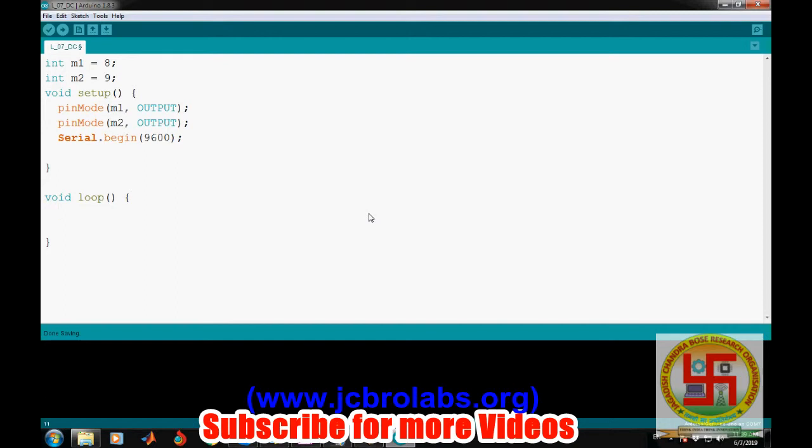What we'll be doing is rotating the DC motor for 1 second in one direction and for 1 second in the opposite direction. That is the simple program which we are going to do. So let's write it. First we need to send 1 at pin number 8 and 0 to pin number 9. So digitalWrite M1 comma HIGH. This pin number 8 will become high, and similarly we have to make pin number 9 low.